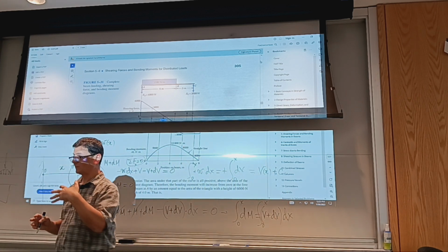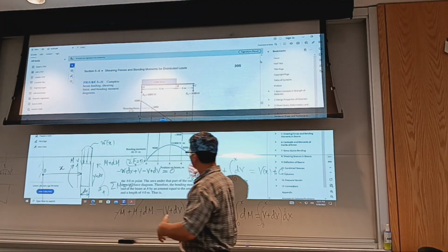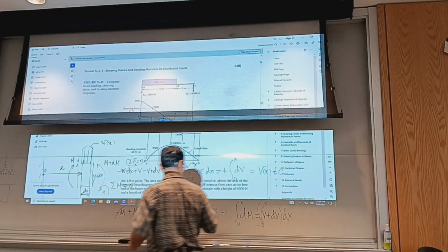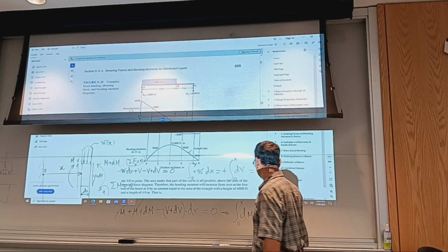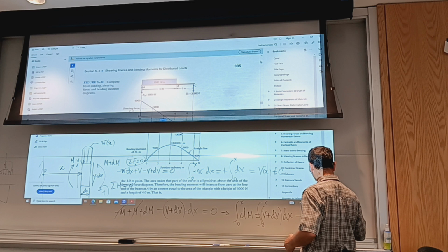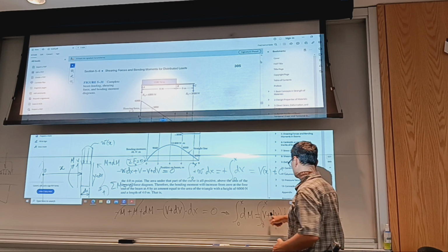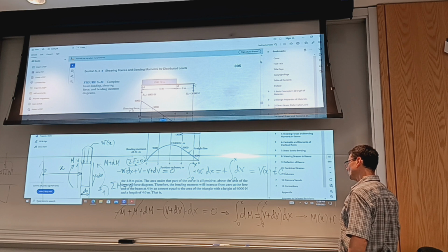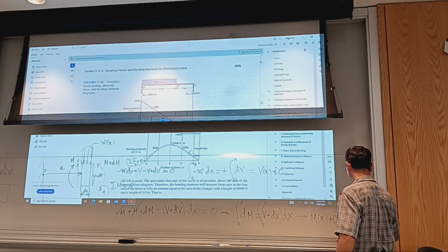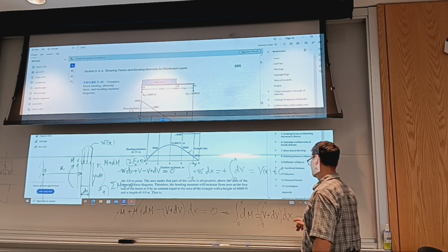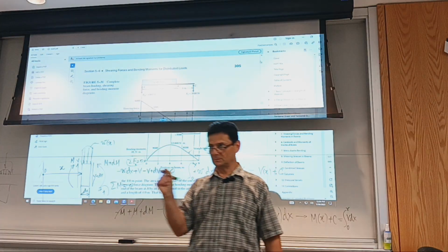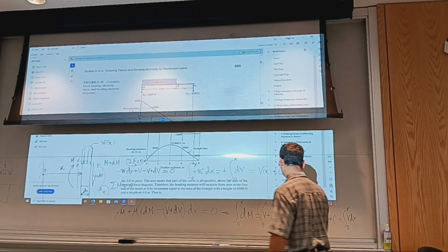And you will see for deflection, we're going to go through these steps, actually moving forward to deflection and slope. Okay, that's for later chapters. So it gets you M at x plus a constant of integration equals to, what would that be? Integral from 0 to x of V dx. And then dV dx, being small, are like two very small amounts that you multiply, you just ignore them.